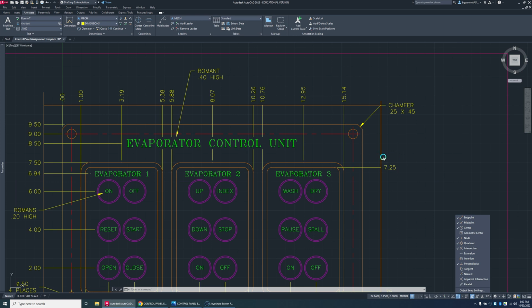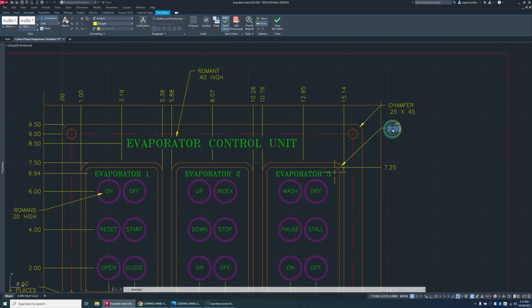And then we're going to go to a radius of 0.5, 12 places, so another radius here. So I go radius, and then this here, that one there, and perpendicular on here. I'm guessing this will snap on there, I won't do perpendicular for these ones. Going across, snap out of that line, nearest. And nearest that, alright, I'll go right here. And I'll go over, and then enter. This is going to be for 12 places, like so.